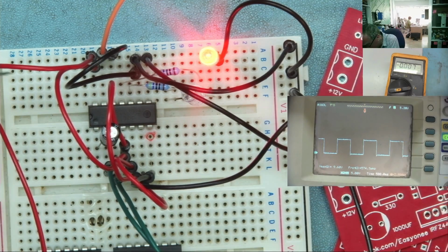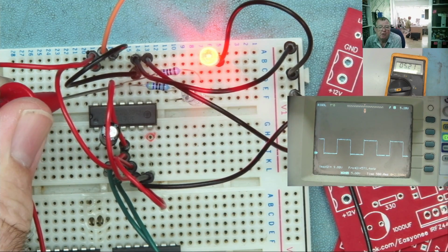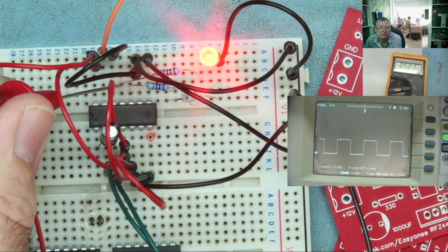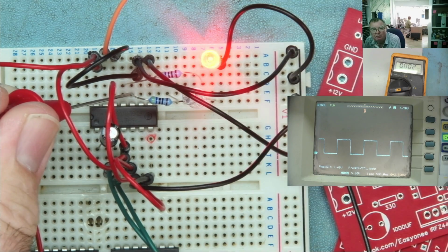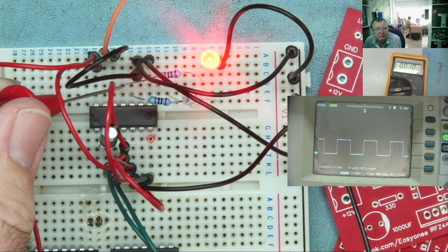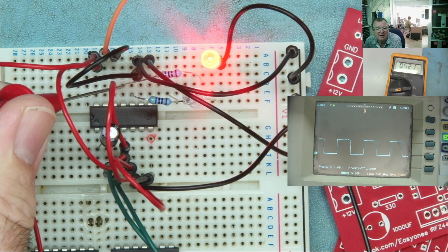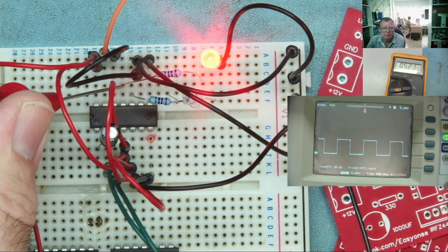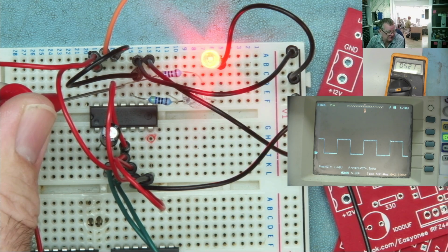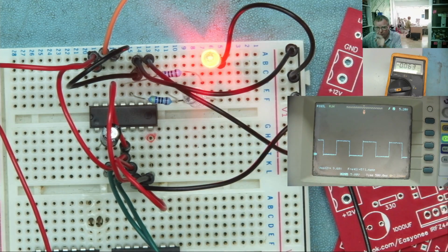What voltage do we have on these LEDs? Well, the one that's on has 5.21 volts on it. And the one that's off is 0, which is what I would expect. So the output here is not actually being held up at the 9 volts. It goes to about 60% or something like that of the voltage. I do know from checking earlier, and we will just check again, that there's no signal on this pin, maybe little spikes. We can just check that though.